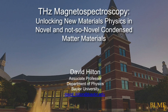Once the signal gets over to the tower, that signal gets turned into something that's put into an optical fiber and fed over to either the landline that you're talking to or the other cell phone. That's a laser that's indium gallium arsenide phosphide. So we're starting to look at materials as indium, gallium, arsenic, and phosphorus. And so that's the type of laser that you would use to couple the signal onto an optical fiber. But basically, all of your communications on a daily basis are about 5 or 6 atoms here.